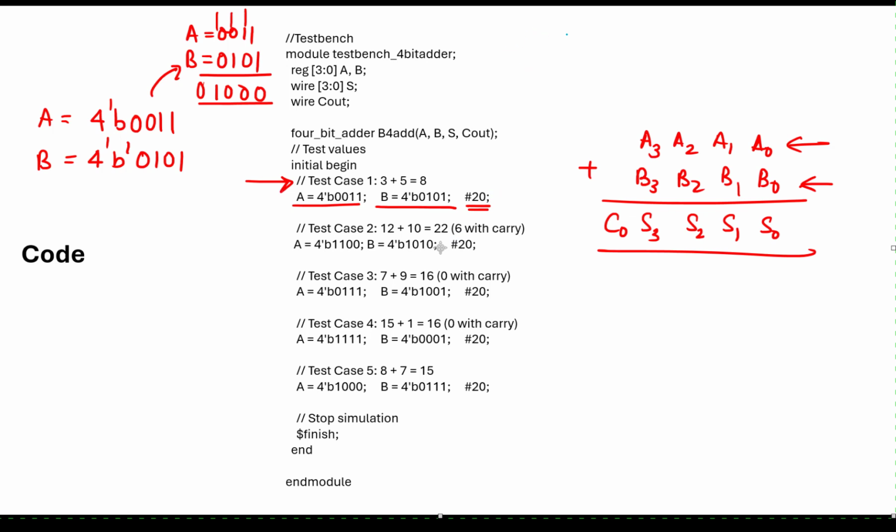By default, on the top of this code, you see something like timescale 1 nanosecond / 1 picosecond. What this basically means is that the default time unit is 1 nanosecond, and the precision of time, meaning the minute incremental values at which you can still observe change in input, is 1 picosecond.